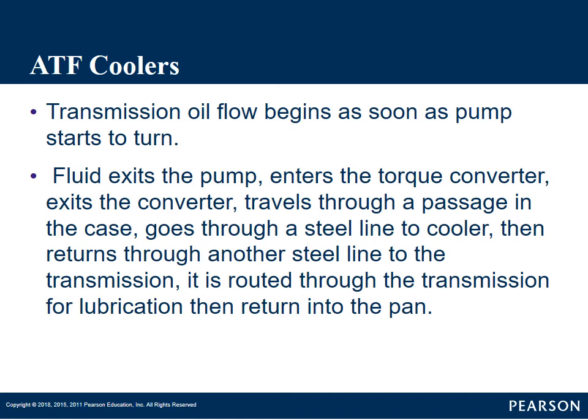And we'll talk more in depth about torque converters, but we need that fluid in the torque converter for that torque converter to even work. That's one of the purposes and functions of transmission fluid. If we did not have fluid pressure in the torque converter, there'd be no fluid coupling in the torque converter, and we wouldn't get any power transfer from our engine into our transmission.